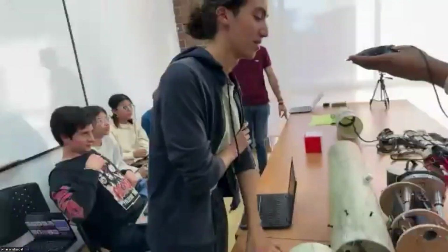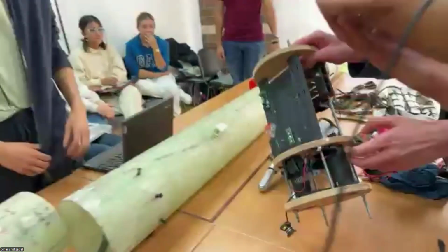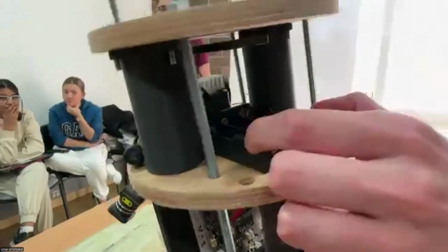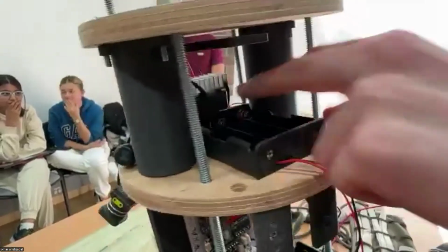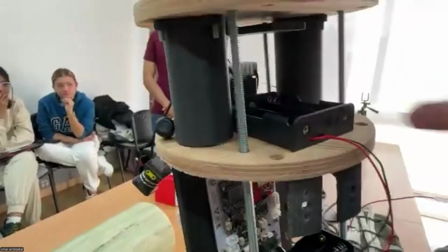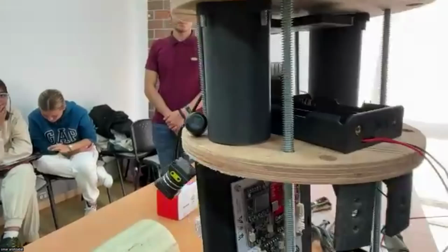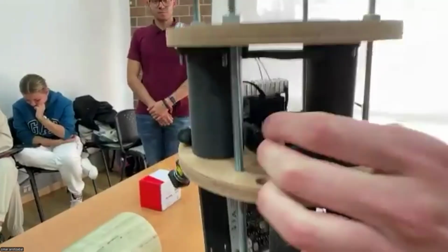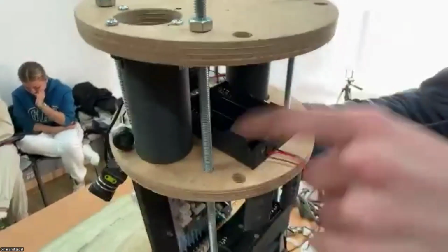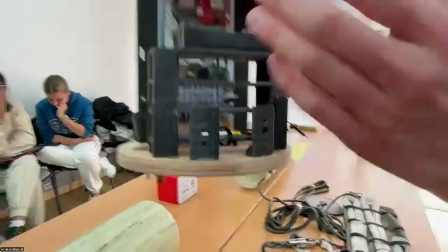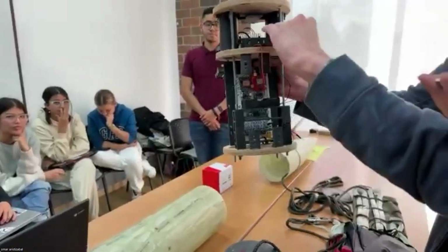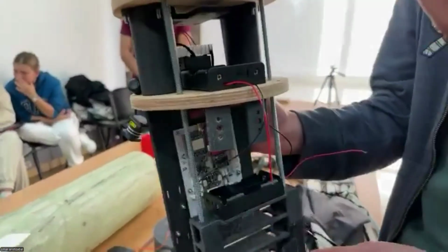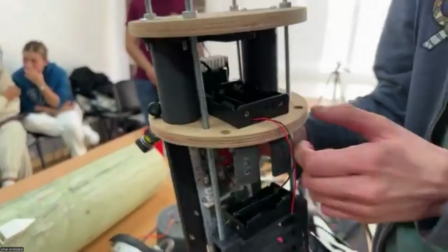For the avionics bay battery holder, we're going to use zip ties at these points and at this point back, and we'll also secure it with tape to make sure the batteries don't come loose due to the forces it's going to experience. The holder is going to be screwed down to the base. As per ESRA requirements, the holder needs to be on the bottom. That's how we're going to set up the battery holder for the avionics.